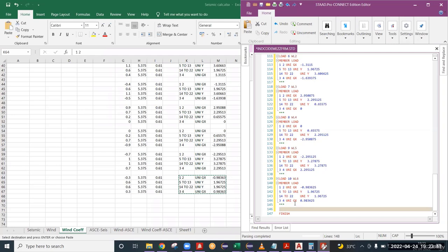Yeah, actually, some industries have boilers. Yes, exactly. Textile mills and some furnaces, blast furnaces. Yes sir, some industries will have these. At that time, you have to apply temperature load. Okay, but how to apply temperature load is that you can apply the same thing as we applied in AISC, but you may have a doubt about what safety factor we have to apply in the combination. That is the same thing.